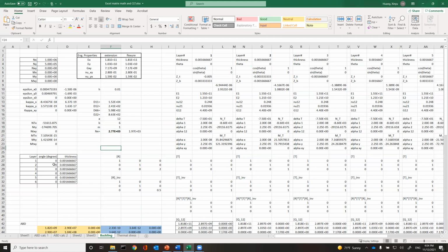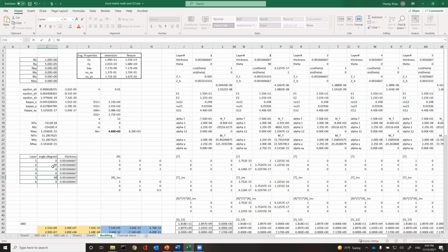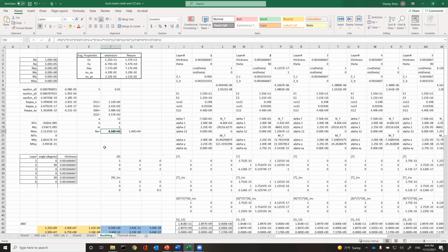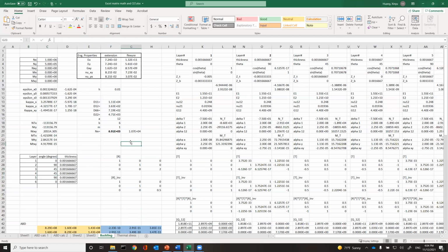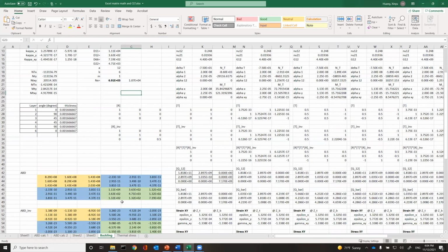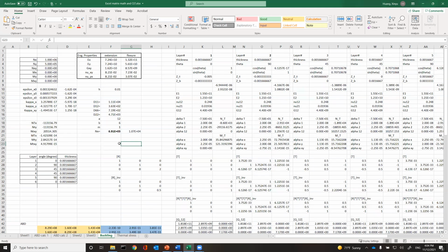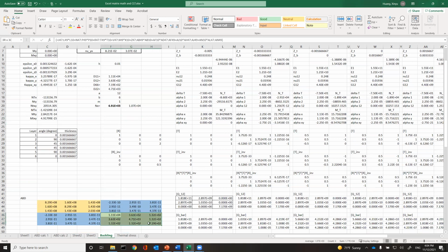And then I can change the ply to, let's say, a cross ply with 90s. I put 2 90 in. The buckling load updates, and you see it's a little higher now. And I can do 45, and so on and so forth. So basically, I just want to point out that you can use this code for this calculation. In case you need it, you first find some solutions, program them in, and then use your CLT to calculate the D matrix, this matrix right here.